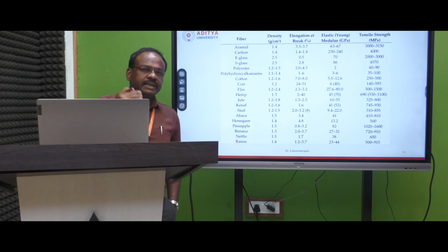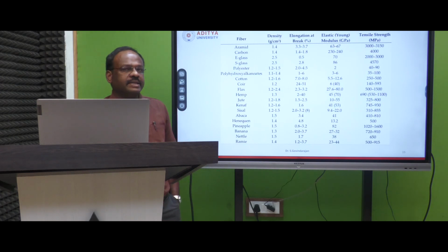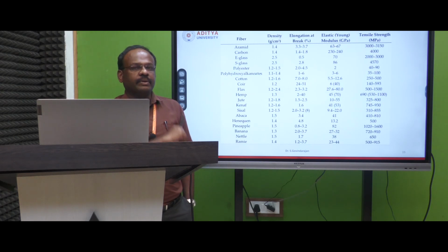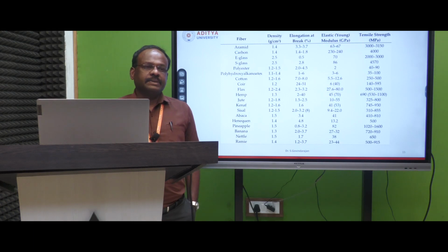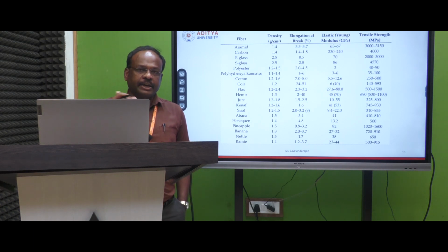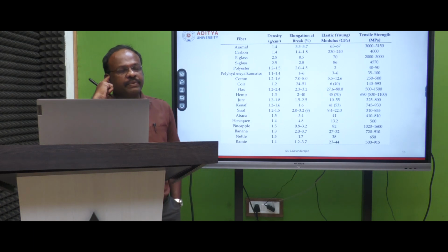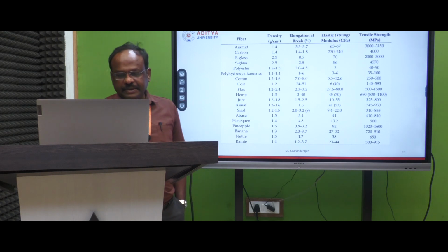So to avoid corrosion, we use alkali resistant fiber reinforced rods. Otherwise, they use a coating material, which is applied on the reinforcement, so corrosion is avoided. For that type, they use alkali resistant glass fiber.